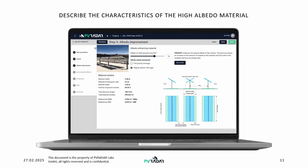In this limited version, we could select between the full ground coverage, which is basically covering the entire area, or the regular pattern with gaps. In this case, we are taking gaps. We are putting the material underneath the modules, and we are also accounting for a material overhang of 0.5 meters each side. So that's the condition we are simulating.